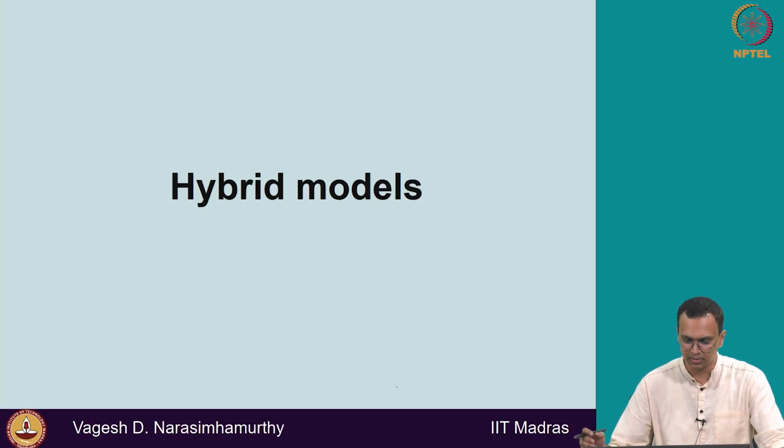So to counter the wall resolved LES problems, instead of modeling LES, that is instead of using a wall function, they thought it's better to mix RANS and LES to our advantage, and that is what is called hybrid turbulence modeling. I'll just give a brief introduction here, what it is about.